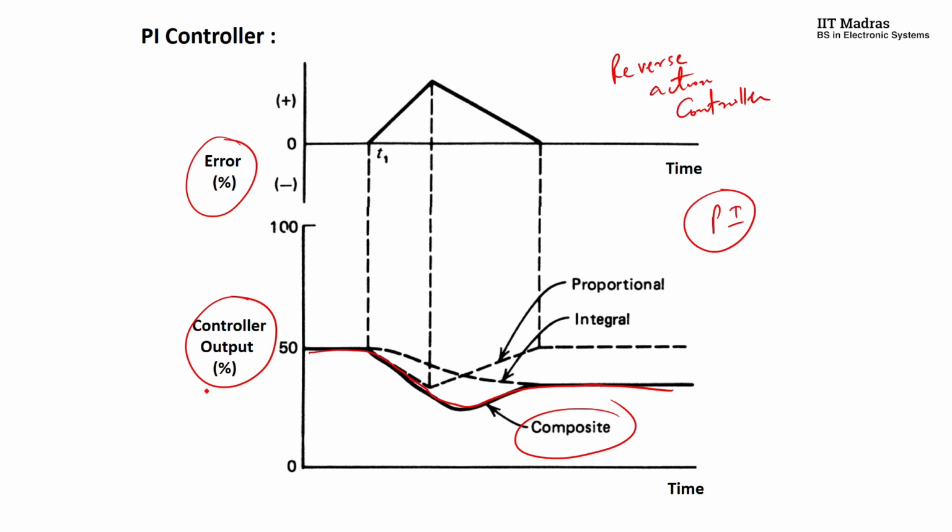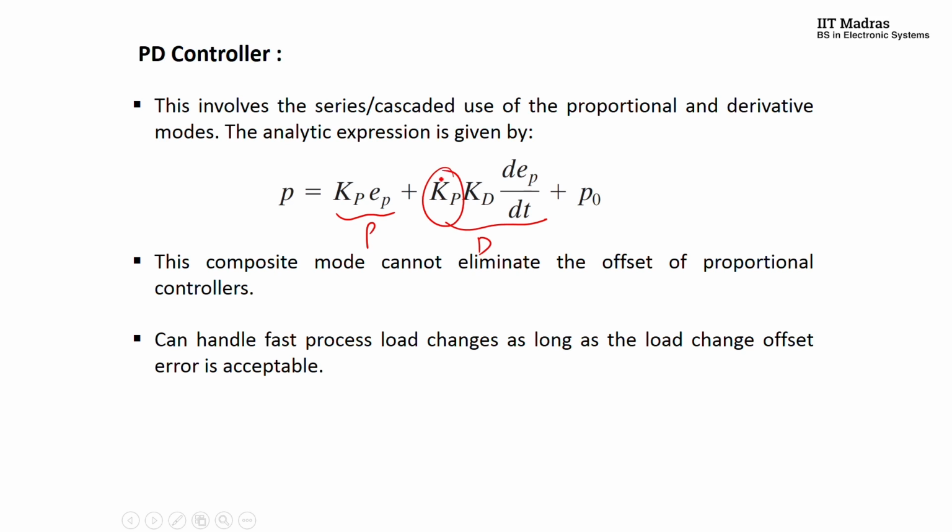So that's the reason why they have given this multiplication factor here, Kp into Kd. As I told you, in a PD controller the main advantage is that the proportional controller is instantaneous and the derivative is anticipatory. However, you will not have any kind of offset reduction because you don't have an integral component here. One depends on the anticipation of the error over time, and the other one is multiplying the error with some gain constant Kp.